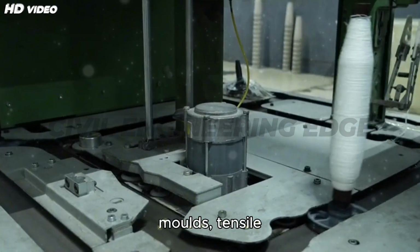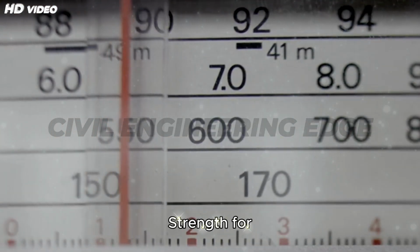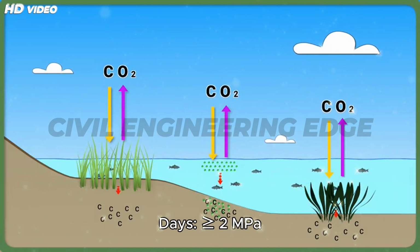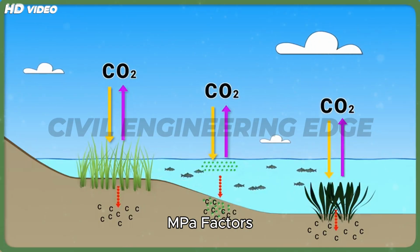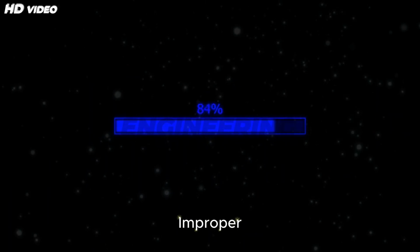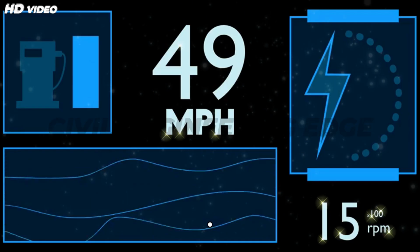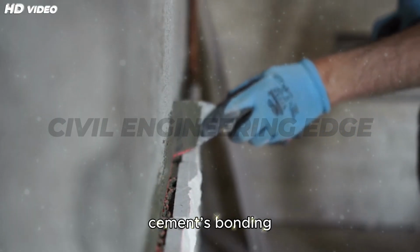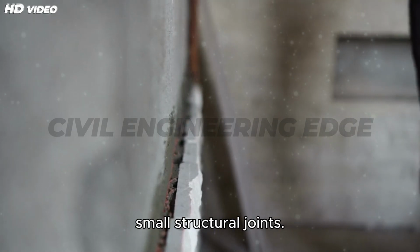Visual: filling molds, tensile machine pulling apart the briquette. Minimum strength for OPC: 3 days, greater than or equal to 2 MPa; 7 days, greater than or equal to 2.5 MPa. Factors affecting results: improper compaction, incorrect water content, temperature and humidity. This test validates cement's bonding power, vital in plaster, masonry, or small structural joints.